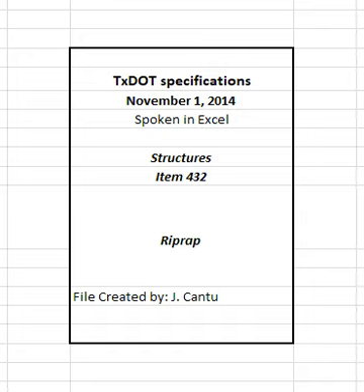Use stones that are at least 3 inches in their least dimension. Use stones that are at least twice as wide as they are thick. When shown on the plans or approved, material may consist of broken concrete removed under the contract or from other approved sources. Cut exposed reinforcement flush with all surfaces before placement of each piece of broken concrete.